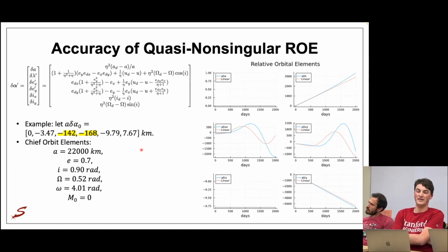It's really increasing the eccentricity that will cause this to become less accurate. If you were to scale it up, it would probably hold up a little bit better, because you're moving the relative perigee around. So they're all pretty far apart. I'm moving the relative eccentricity part, which means the argument of perigee is going to rotate at different rates for each of them, and that causes the linearization not to hold up too well. So you have to be a little bit careful by increasing that.